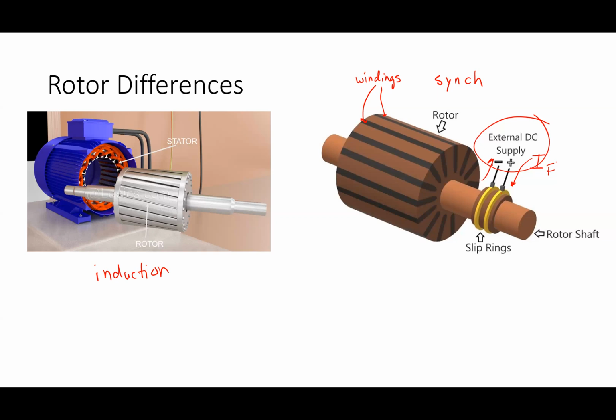But instead of a field winding, what they have is magnets, right? There's magnets inside of that rotor. That would totally work the same. What that field winding is doing is you put a DC current into it, and it makes this rotor look like a magnet, effectively. So I could do the same thing without having the slip rings if I put magnets inside the rotor. So that is also a feasible thing to do. We'll look at that towards the very, very end.